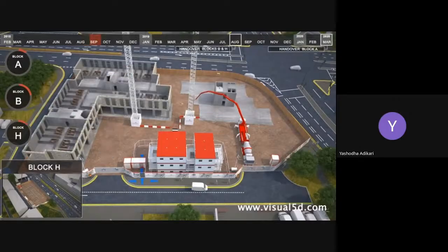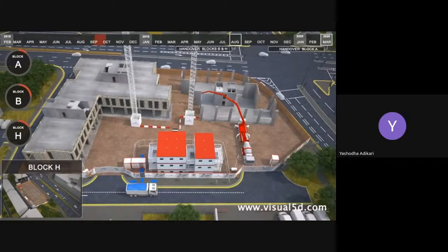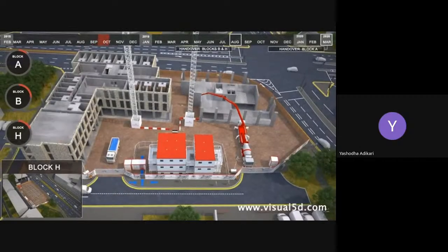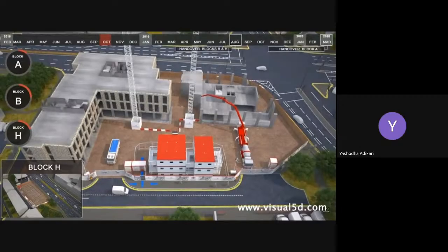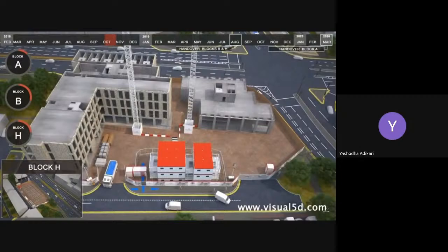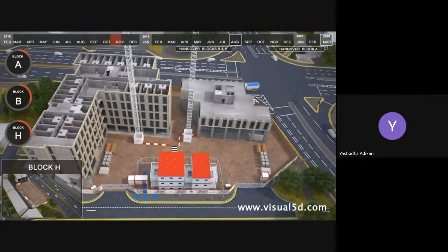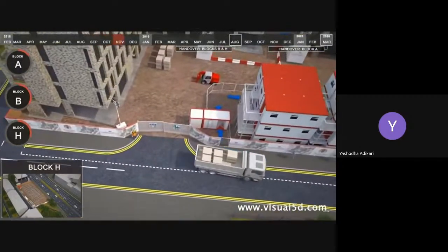The next element of works will be for the precast frame to Block B to commence off first floor podium level. Whilst we complete the in situ concrete works to podium levels of Block A, we will utilise the 2 cranes at this point to secure a programme advantage on Block B. Block H will be constructed with a combination of steelwork, precast planks and a more traditional method of brick and block work. This will be built concurrently to Block B, with both Blocks B and H completing in August 2019.